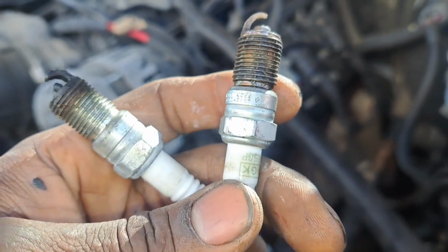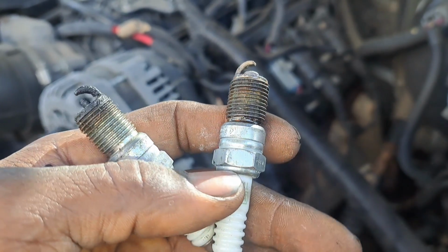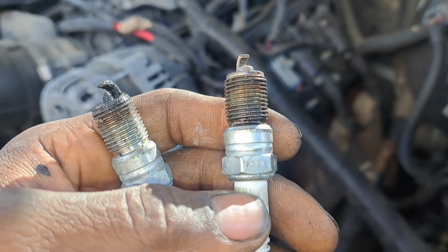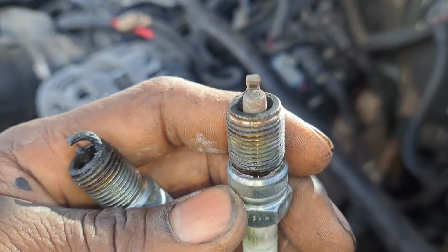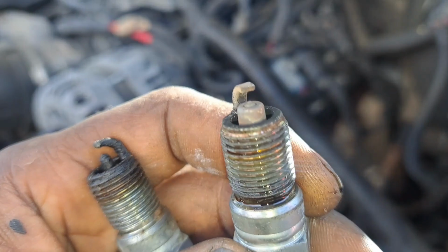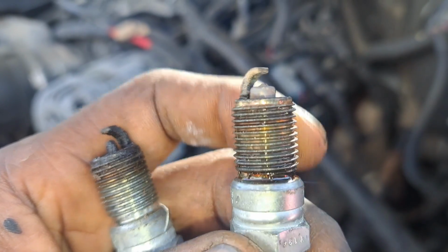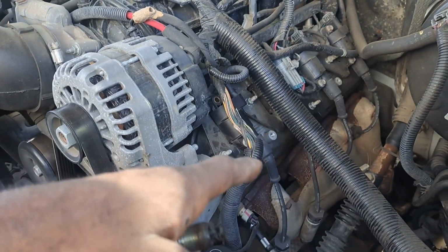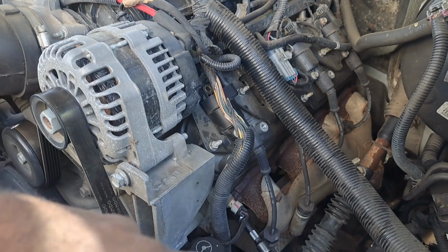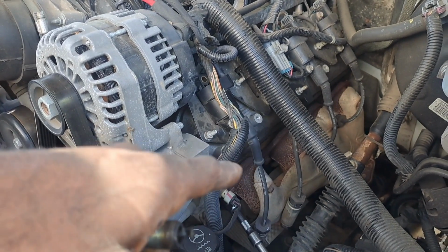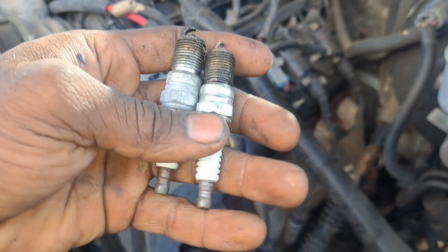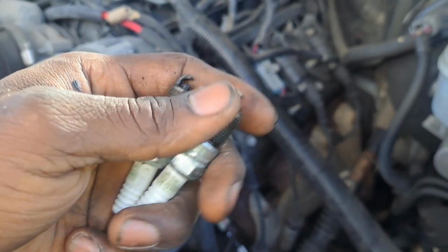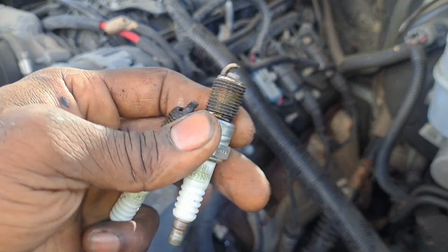Here's the original plug on 3. I think they're numbered like that on this one. So 1, the next one is 3, and look at that gap. It burns good, but the gap is extremely excessive. So I'm going to bring the maintenance up on here and replace the plugs. I think I can get away without replacing the wires, but I'm going to buy a wire set just in case, and I'm going to test drive it again and see if that fuel trim and balance code still persists.